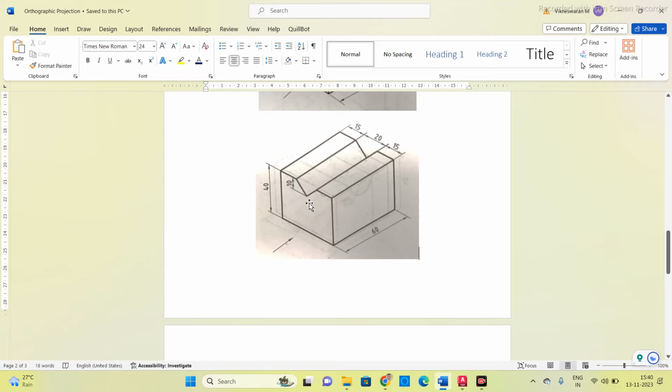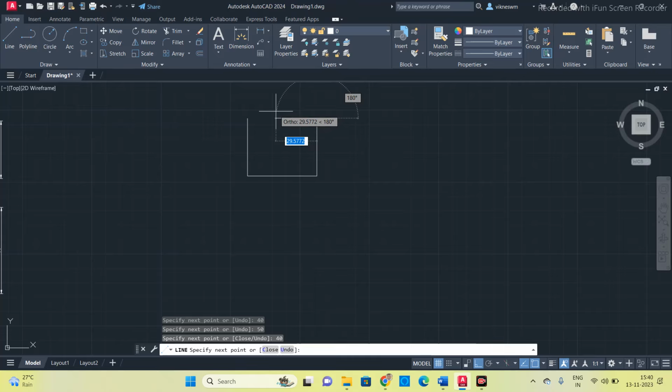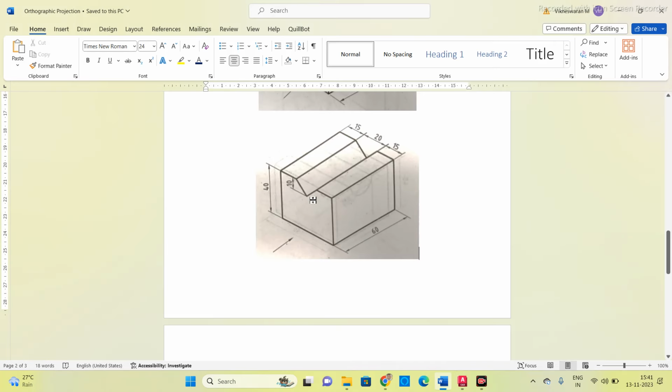Now so here the V groove is given here. So it is 15 mm from the edge on the outer, the V is starting from 15 mm from the outer edges of the top face. So what I am going to do, on both sides I am going to draw a line for 15 mm. Now we have to locate this base point of this V, and then we have to connect the corners from the top line. Okay. This height is 10 mm.